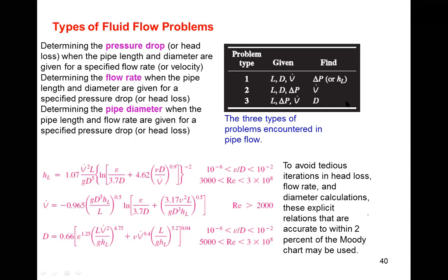And in that case, you have designed a pipeline for the liquid, and now it is converted to vapor. So your pump and everything would fail. So you have to make sure of the pressure inside the pipeline. First thing, it should always be more than the vapor pressure of the fluid at the given temperature condition, in order to avoid vaporization, so that it is not converted to gas.